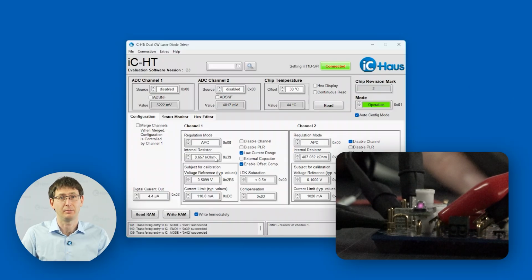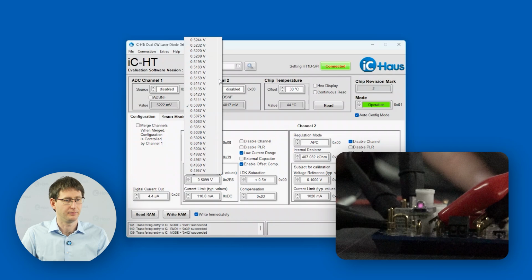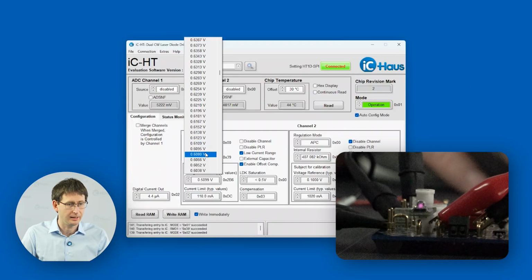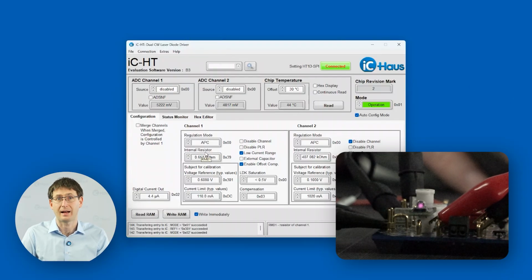Best practice for a stable control circuit is to stay within 400 to 600 millivolt. A higher value here increases the output power and a lower value decreases it. Just to have a quick look how the fine-tuning works, when set to 600 millivolts instead of the 500 millivolts, the current drawn increases to 35 milliamps. This will yield a significant power increase.